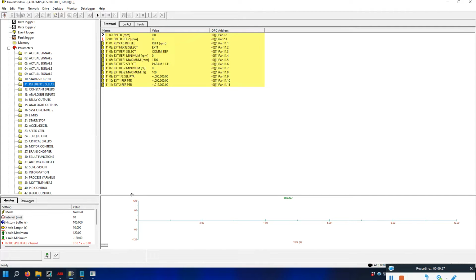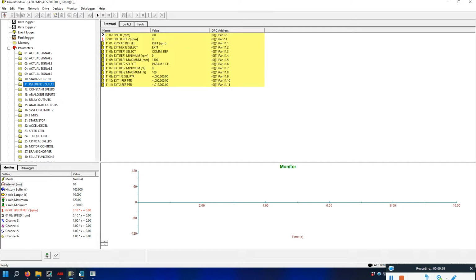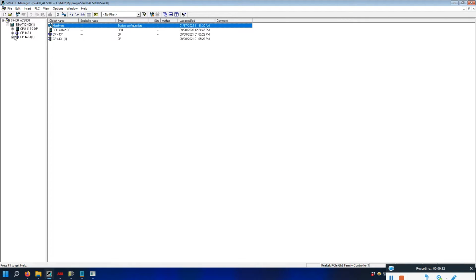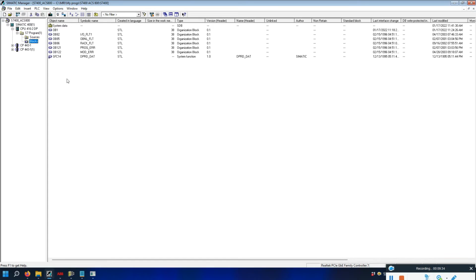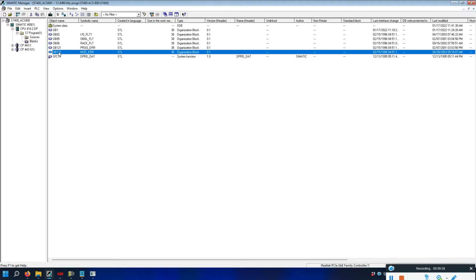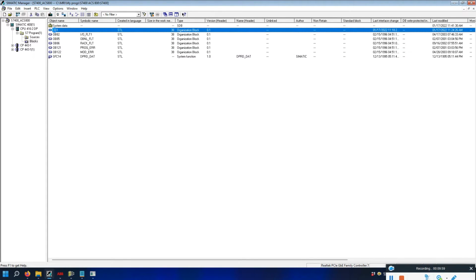Now we will go to the PLC program. So if you want you can put these OB blocks, because this depends on your requirement. If you have some IO fault, track fault, everything, this will bypass all that. So if you want you can keep this OB, just add this OB number 82, 85, 86, 121, 122, otherwise leave it. Okay, so we will write the program in OB1.